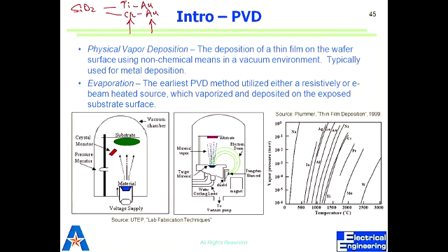So what do we do in PVD? We melt our material and let the vapors travel to our substrate. I don't want vapors to travel here and there, so I want them to travel in a straight line. I want to increase the mean free path. What is mean free path? It's the distance between 2 collisions. How do we increase mean free path? Vacuum. So I do it in ultra high vacuum.